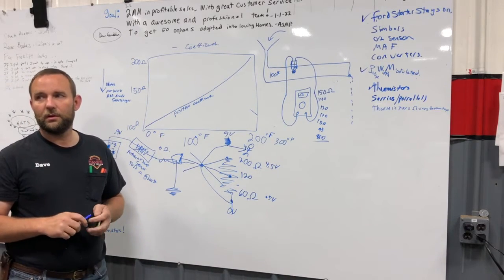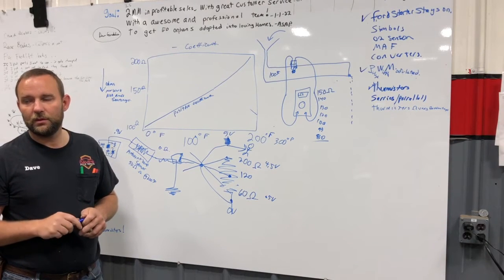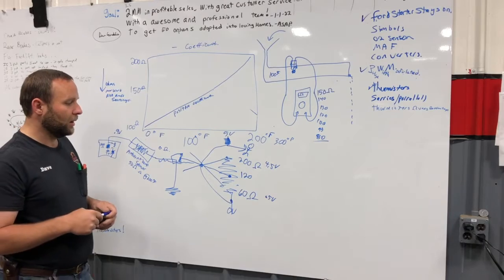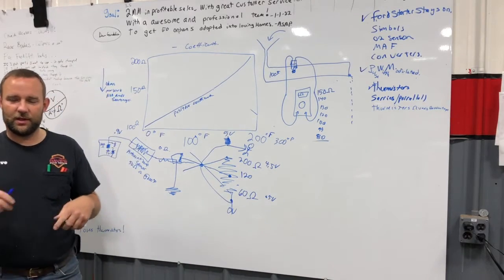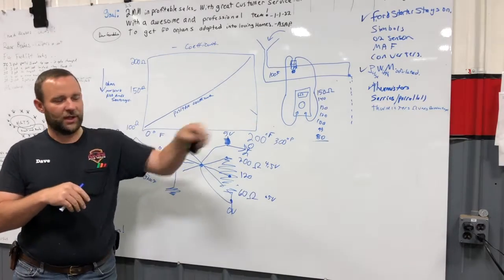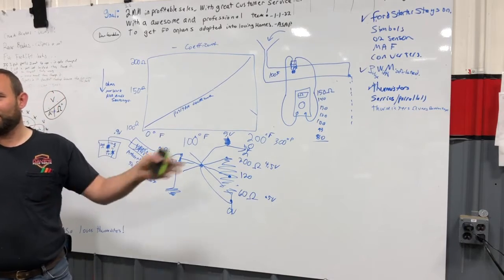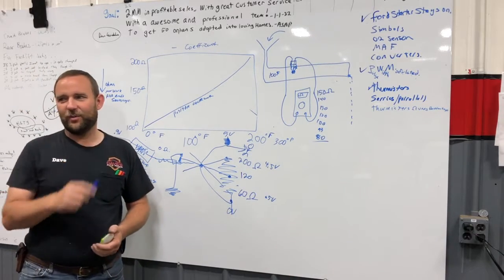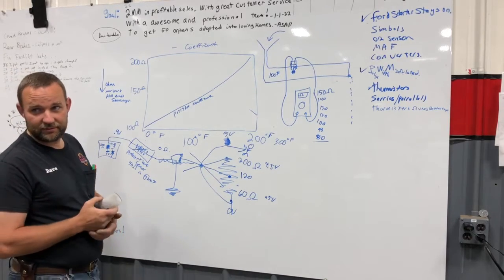You could actually prove it. In some vehicles, you unplug them, they go full one way, or ground, I forget which way it is. One way or the other way to prove the system. So I have an actual fuel gauge tool that I have back probes on. You unplug it, plug this thing in, and look at the gauge. I kept one, put long wires on it. I have a whole box of stuff up there. So that's how a fuel gauge works. Does that make sense?